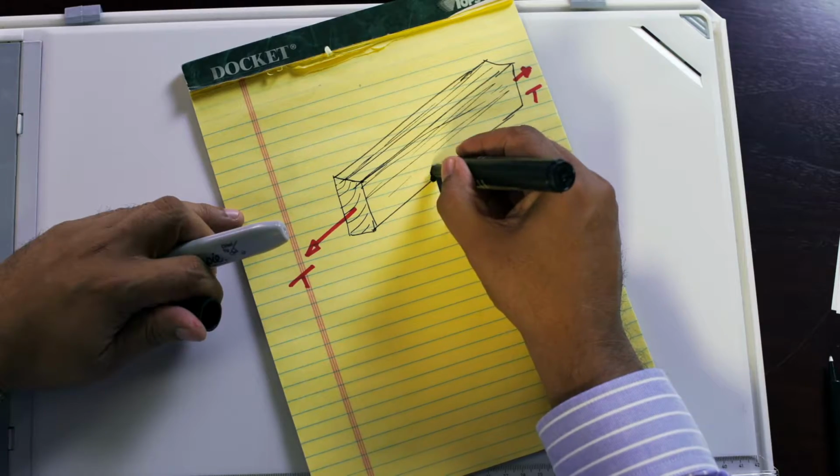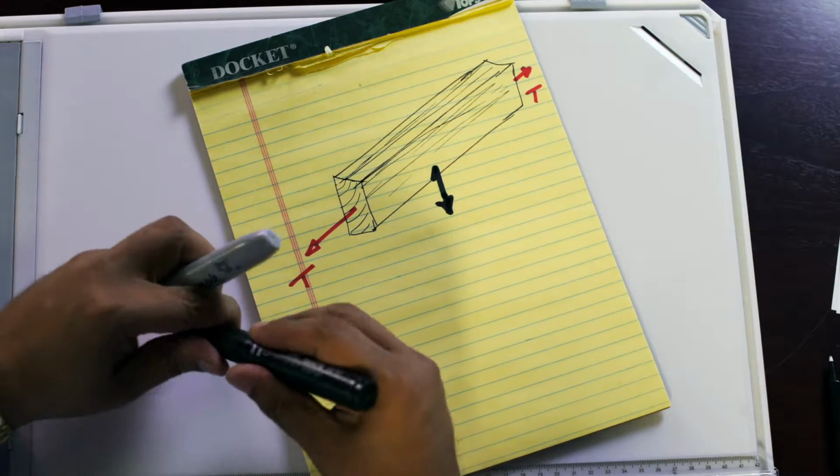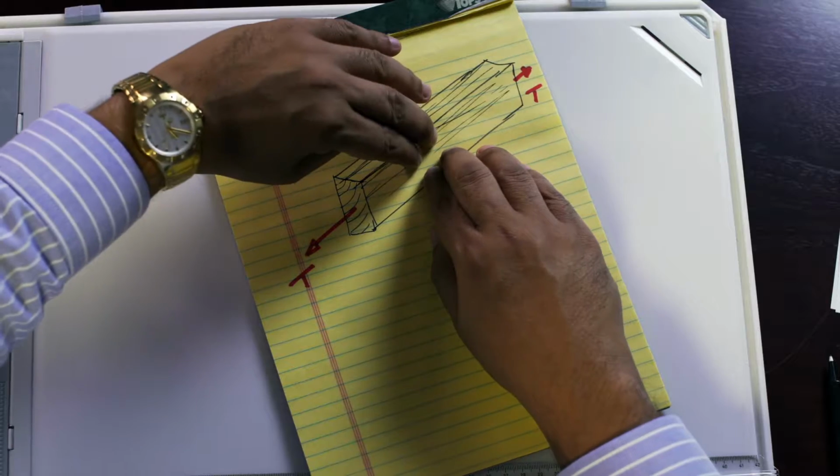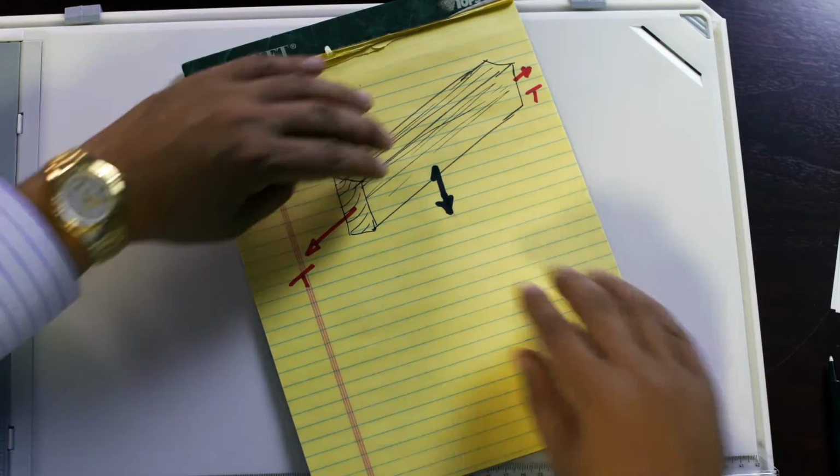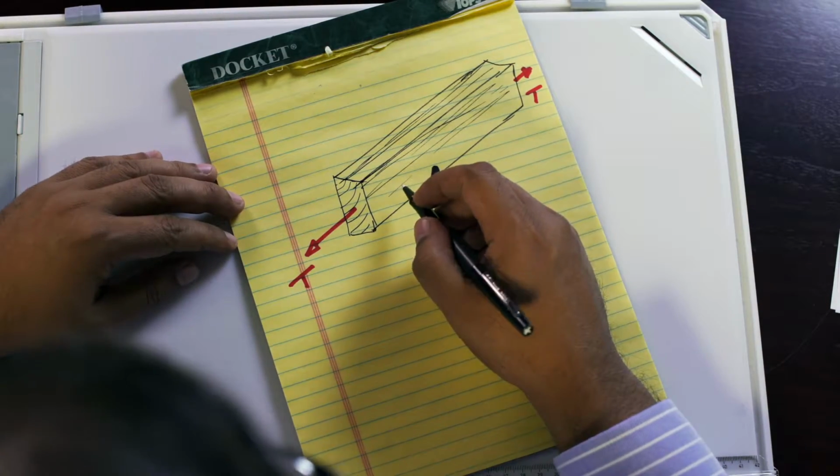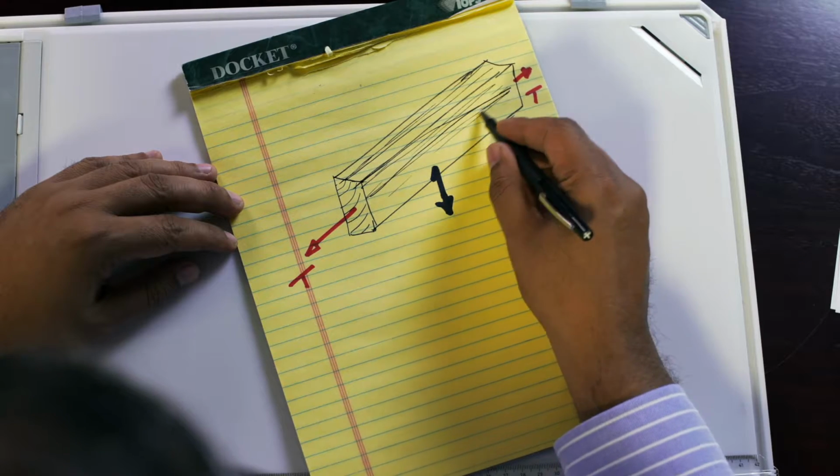But if I try to stress it perpendicular to the grain, in other words, if I'm stressing it perpendicular to the fibers, wood is not such a great material. The wood will separate because it's very weak perpendicular to the grain. So one of the main things about working with wood is understanding this phenomenon, that it is not like steel, it is not like concrete.